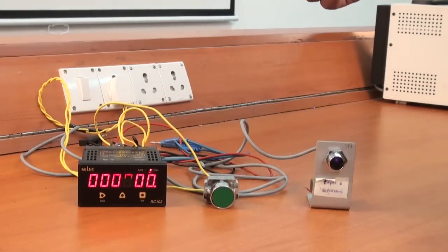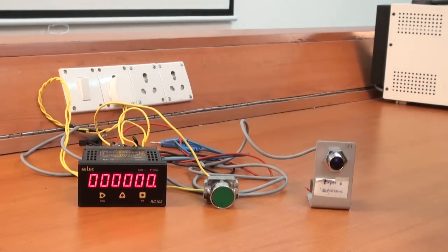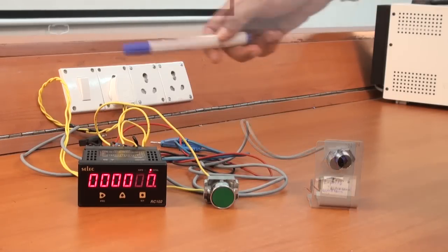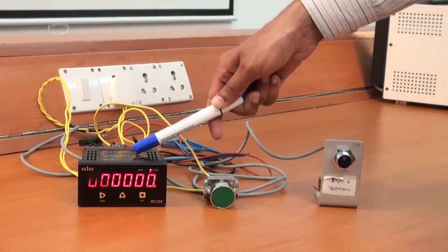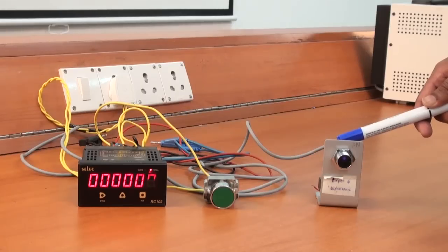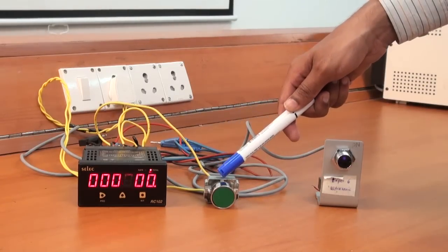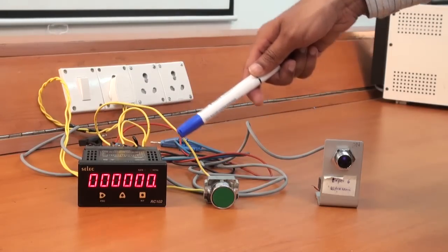We have another kit having a counter or totalizer unit which is used to count finished products in bottling plants, food processing plants, cement plants, to count bags, bottles and different cartons. This is the counter unit in which we can give input from a rotary encoder, limit switch or this type of optical proximity sensor. This is a push button for resetting of the counter. We can reset the counter through a remote terminal or from the keypad.